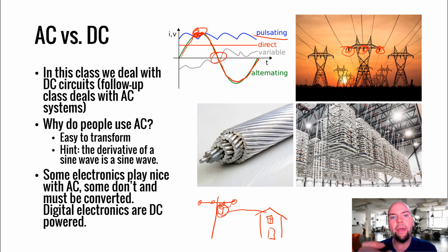So a better way: you can transfer a lot more power if you have DC that's the exact same voltage as that peak AC on the same conductor infrastructure. And there are countries that do that. High voltage DC transmission is something that some countries have experimented with. Although, again, there's this issue of transforming it.